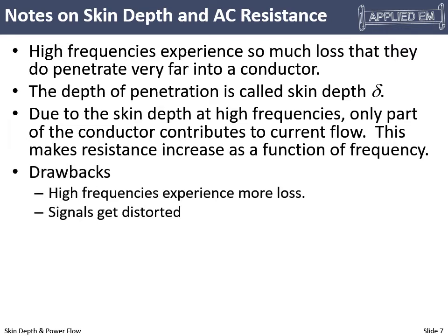Now the drawback of this is that high frequencies experience more loss. They're not utilizing all of the conductor. This also means that how much loss there is becomes frequency dependent, and so this also distorts our signals. That's bad. Now you might be surprised that skin depth actually does have some advantages.